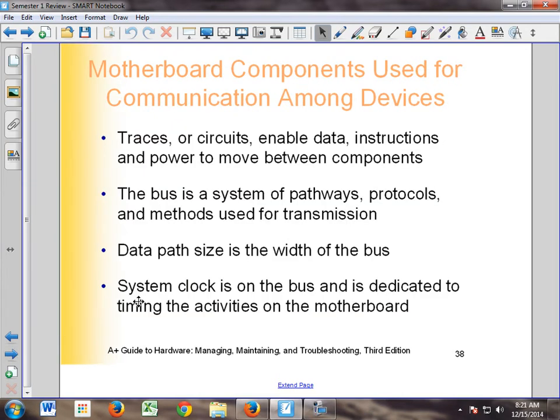The bus is how the data goes around between the individual items in the CPU, and the width of the bus right now can either be 32 or 64-bit. Newer is 64-bit, but most things are still 32-bit, and it travels around at a speed determined by the system clock. The clock starts pulsing. That was the number 2 thing that happens when we push our button and turn on our PC.